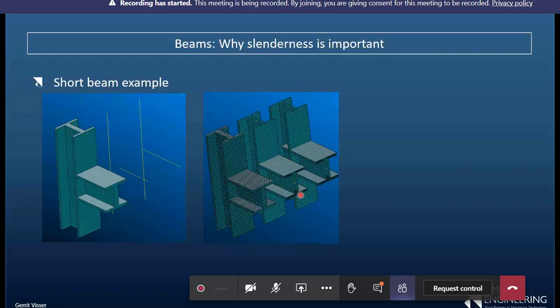If you need to mesh that fine and the answers still keep on changing, then you're not inside shell theory. But if you mesh finer and finer, the answer will converge. It will stop at some point, but usually the solver will tell you that there is an issue, but that's due to round-off errors that start causing problems. Before that starts, the solver will already stop and not run the analysis. I did a test a long time ago, and it was something like one beam element section. If you model that with 100,000 elements or something insane, that's more or less when I started running into that kind of an issue.